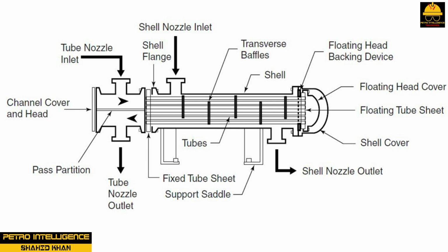Adding fins to the tubes can further enhance heat transfer. An impingement baffle or pass partition is located between the tubes and shell inlet. This redirects the flow and keeps the tubes from being damaged. This type of heat exchanger produces the highest heat transfer efficiency. Floating head exchangers, with their high cross-sectional areas or fins, are designed for high temperature differentials and high flow rates.